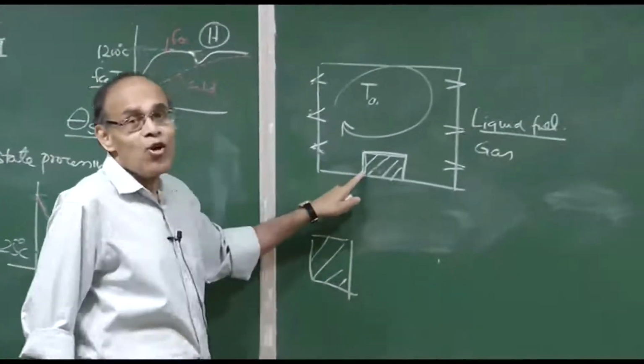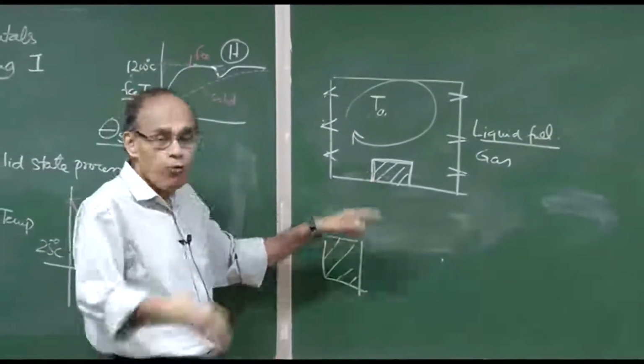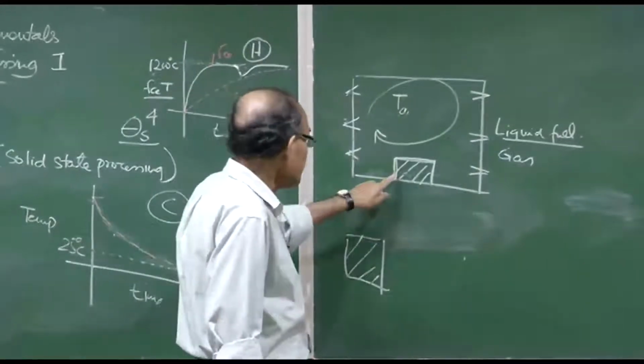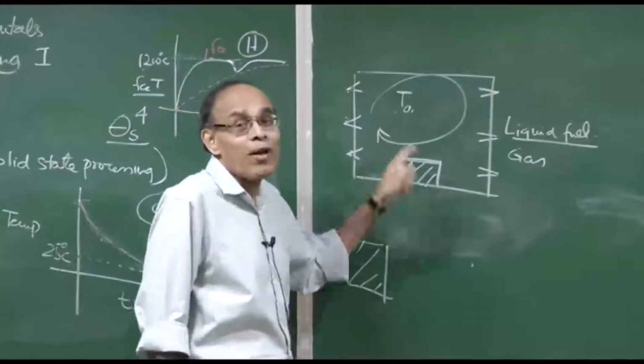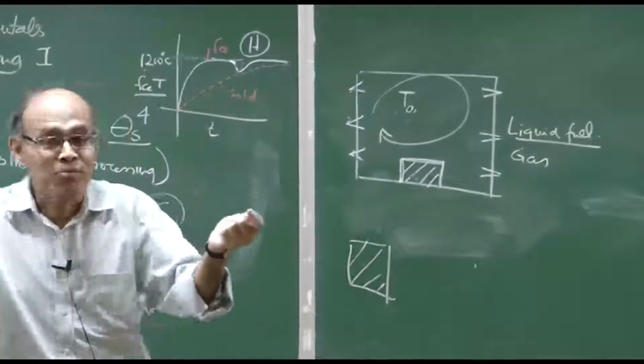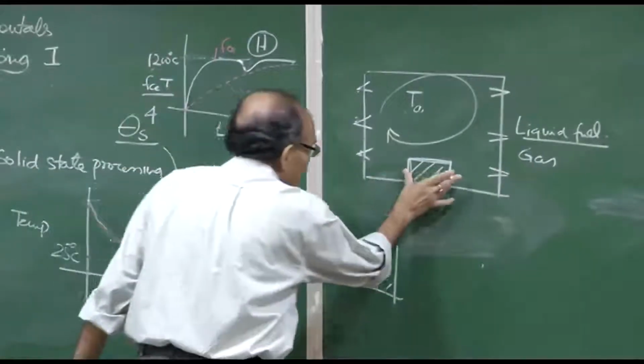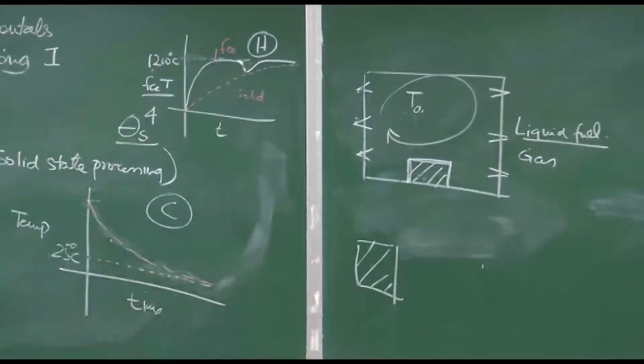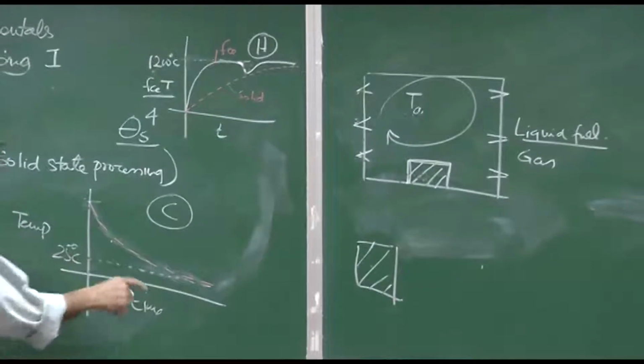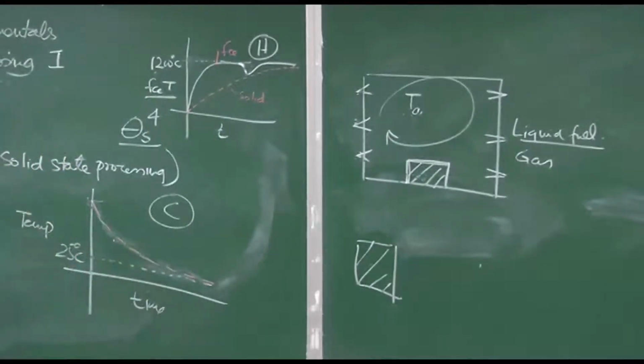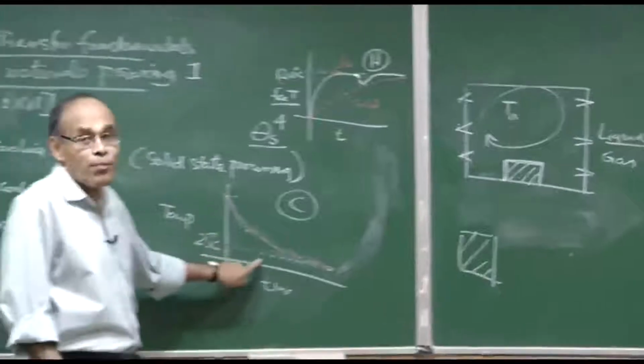So that I do not do any arbitration. If I go to 4 o'clock, there will also be equilibrium, but by then I have lost quite a bit of time. So, pinpointing the time at which the homogenized temperature is obtained is very important for us. Similarly, here we would like to know at what time the center of the ingot attains the room temperature itself.